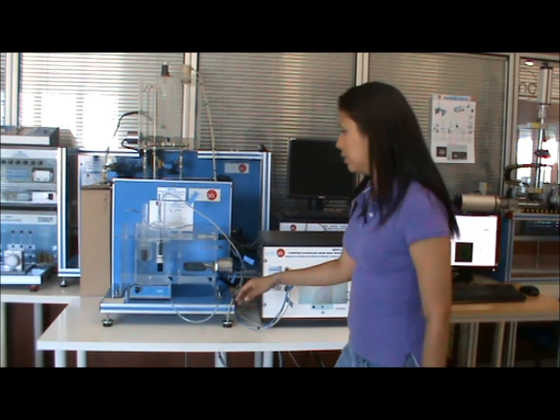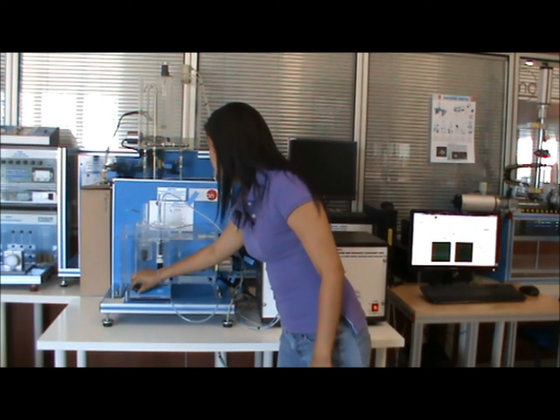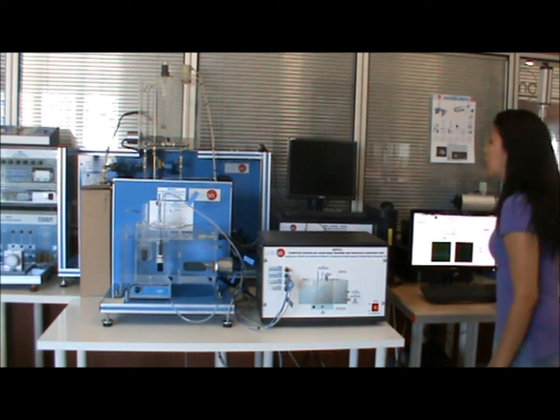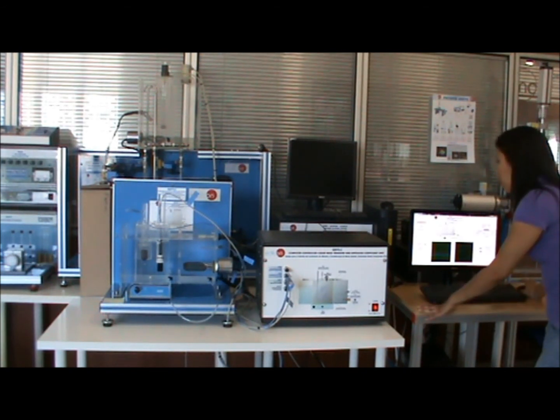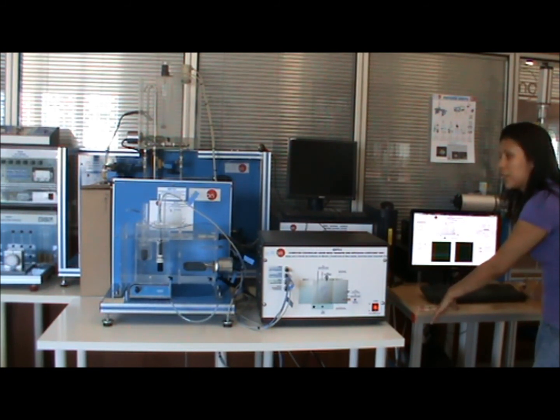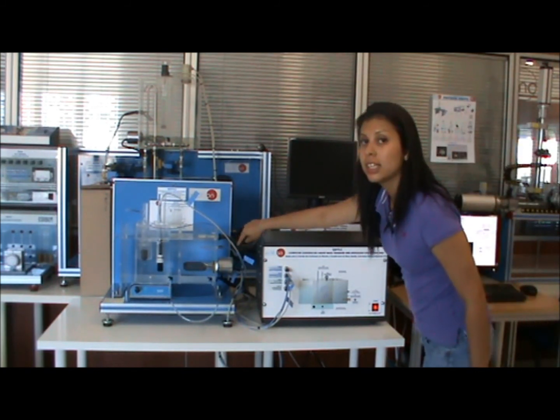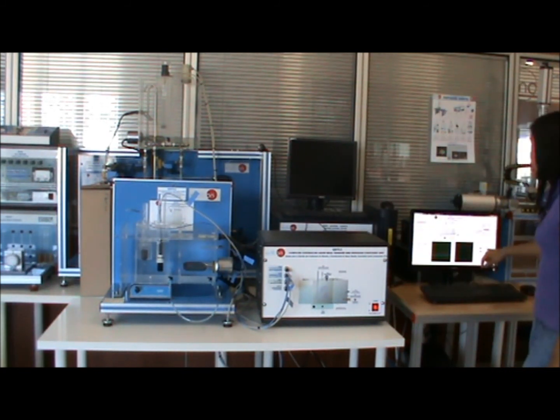Once that is done, you are going to start the software and begin the experiment. You're going to click start. You're going to set the temperature of the resistance that is down here to 20. And you're going to check the mark that says PID on AR1 ST1 set point.